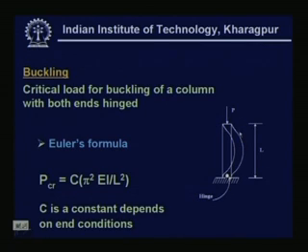The column structure will again regain its original position. So, this is some sort of stability which comes into the picture whenever we design a machine element having a slender column like that. One example you will be learning later on could be a screw for a screw jack, which requires to be designed for a buckling load. This is just one example I am trying to give you.